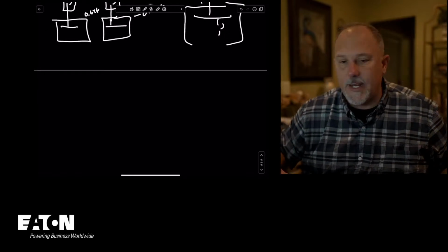And then you can change your design a little bit. So what we did, we reflected the current, we picked the primary overcurrent device, and then we changed the secondary, put that 2,000 amp breaker in on the secondary in its own enclosure. The incident energy was reduced to a very nice value. You could also elect to do two 1,200 amp breakers. I'm not sure what two 1,200 amp breakers would cost as opposed to one 2,000 amp. But in any case, all of those are the different design decisions that we can make.